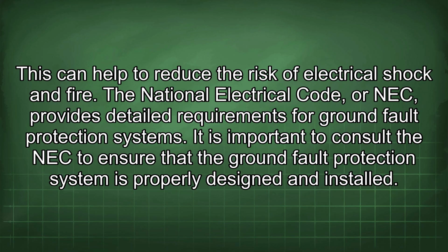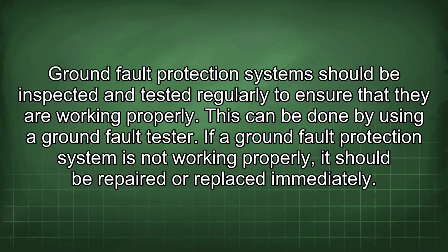The National Electrical Code, or NEC, provides detailed requirements for ground fault protection systems. It is important to consult the NEC to ensure that the ground fault protection system is properly designed and installed. Ground fault protection systems should be inspected and tested regularly to ensure that they are working properly. This can be done by using a ground fault tester. If a ground fault protection system is not working properly, it should be repaired or replaced immediately.